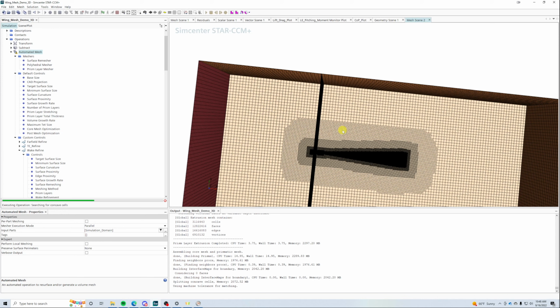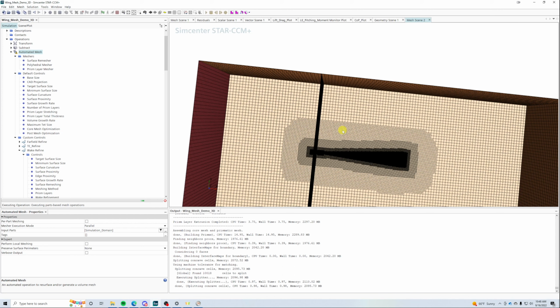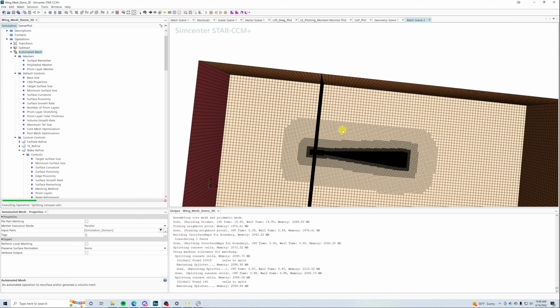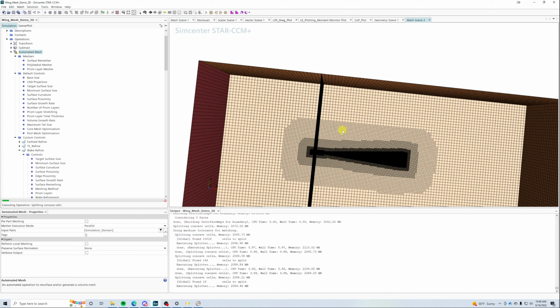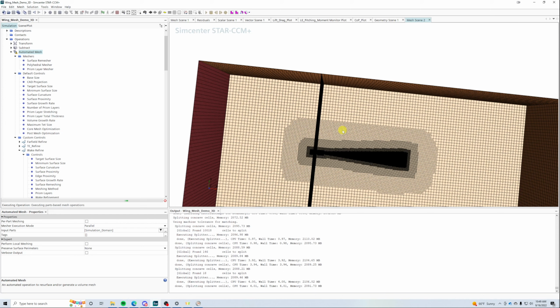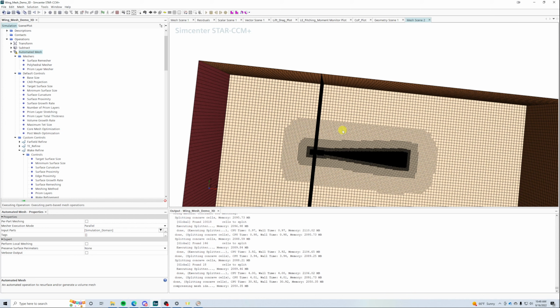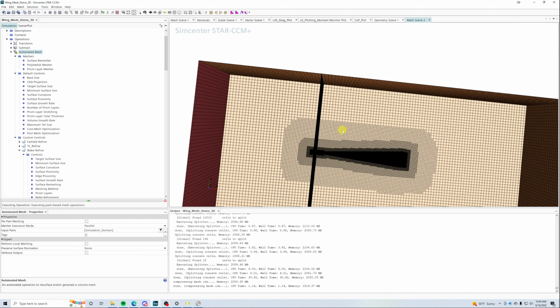In your case, though, we're probably memory limited, which means we need to be much more careful about the number of cells. Keeping it below probably 7 or 8 million is going to be necessary for most of the equipment that you probably use. More robust machines can run more, certainly, but for the applications that you will develop, you shouldn't need more.